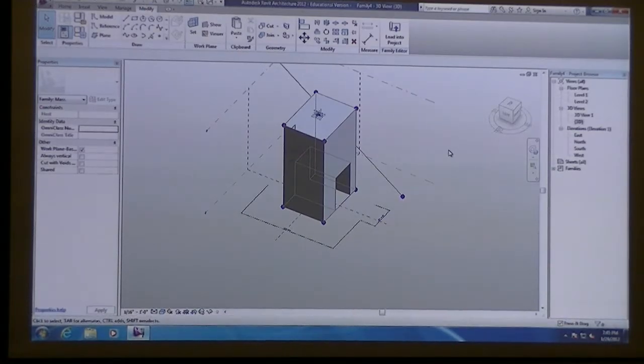So next time we'll meet is Tuesday, and for your assignment, I basically want you guys to pretty much complete your model just with the plane surfaces. That means you should have most of your curves already established. You should have your complex surfaces created for your funky foam pieces. If you're still having problems with making those loft together, you might want to try that adaptive component set of commands that we just went over tonight and try lofting it that way. Then you're going to want to just create your wall component and your platforms, and probably want them associated with some sort of plane that could eventually move up and down.